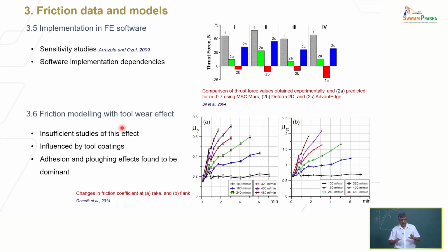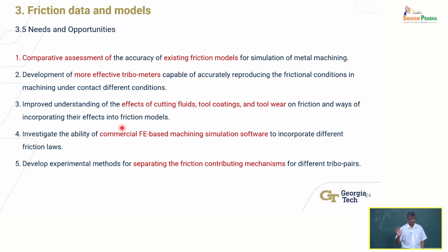Okay, so I'm skeptical of what these models, even if they have them in software, can really do. Okay, I wouldn't rely on it. Force prediction, fine. Temperature prediction, reasonable. These kinds of things are fine today. So that suggests to you that it's still an open issue how to predict tool wear in a practically relevant manner.